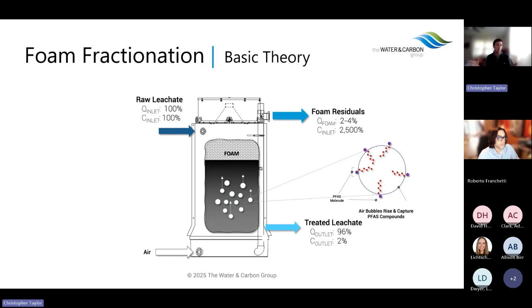You're going to have a major bulk concentration at the surface because you have a lot of PFAS in your leachate. With a lot of disturbance on the surface from all those headstands, you get a major reduction in surface tension. We all know water has a high surface tension, right? When you have a bunch of surfactants on the surface, you're breaking the surface tension. You are greatly reducing it.